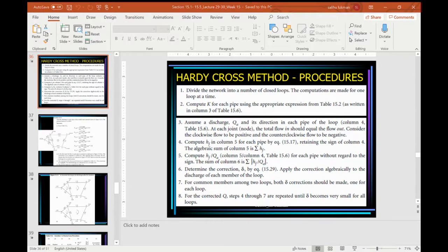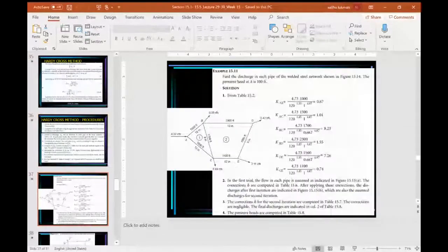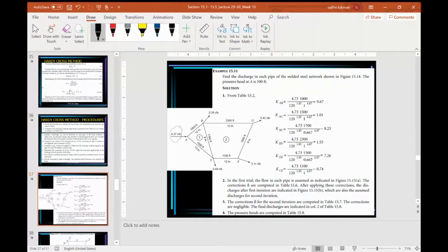If you may recall, in our previous lecture, we tried to perform pipe network analysis. And what is pipe network analysis? Basically, we have a pipe distribution network in which we have total inflow into the network, which could be from a service reservoir, from water distribution system, and we have the estimated outflows at nodal demands at each node.